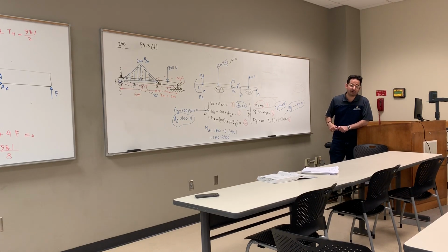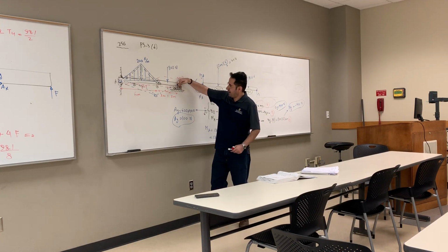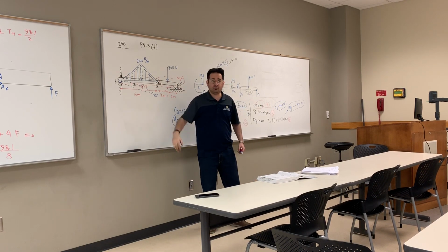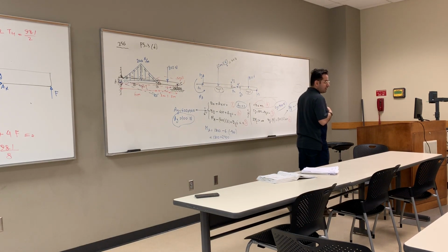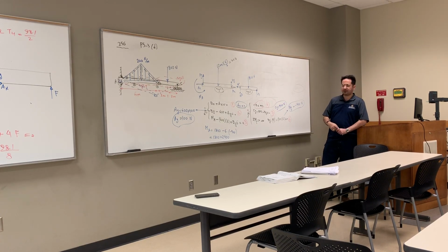If it's negative 400, then you say, how come this force is negative? That means this roller needs to apply a negative force in order to keep this in equilibrium. Is that physical? No. So I'm doing something wrong. But right now, it doesn't look like it's terribly wrong.